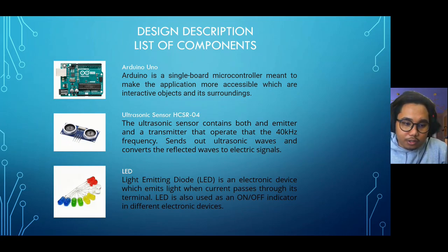Next, we are using ultrasonic sensor. So ultrasonic sensor contains both an emitter and a receiver that operates at the 40 kHz frequency, sends out ultrasonic waves and converts the reflected wave to an electric signal.